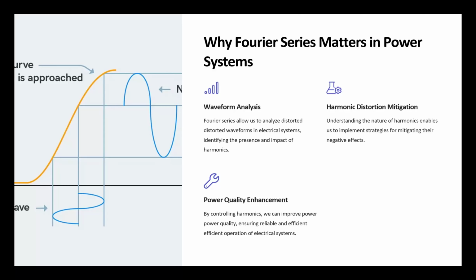Okay, so in reality, what you see is a bunch of ripples on the rotation of your motor. Because 60 hertz wanted to have a smooth rotation, but that 180 would kick in once in a while, and you have a distorted rotation. It's always ripples. Now imagine we have the fifth harmonic, another ripple, the seventh harmonic. You know what I'm saying? So it would disturb the quality of the power you get and you use. Make sense? This is from the voltage part.